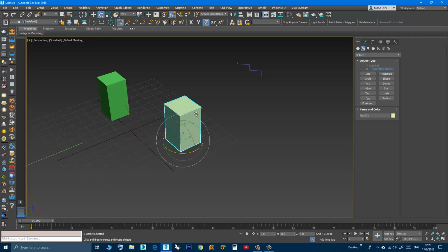If I want to change this default of 5 degrees, I can right click here on the grid and snap settings, options. I have this setting here, angle. I can make it, let's say 15, then close. Now it's jumping by 15 degrees. Right click, I will put it back at its default of 5.